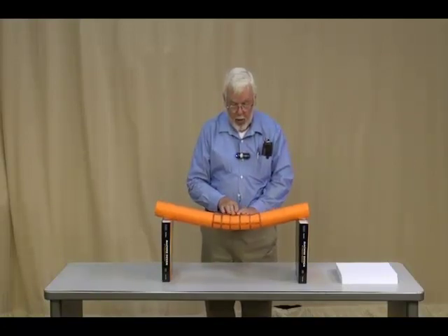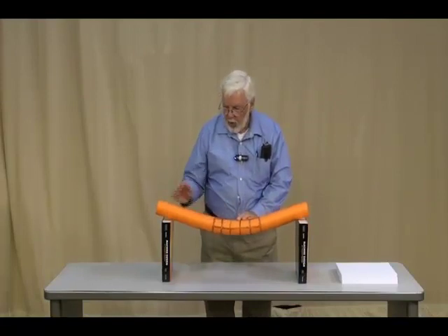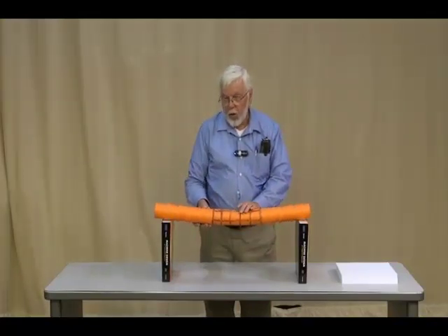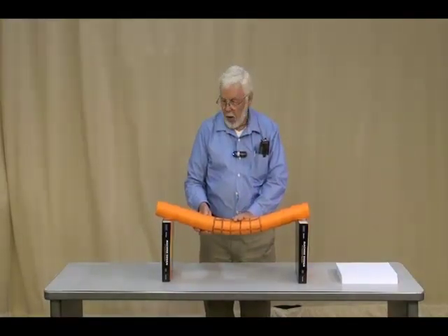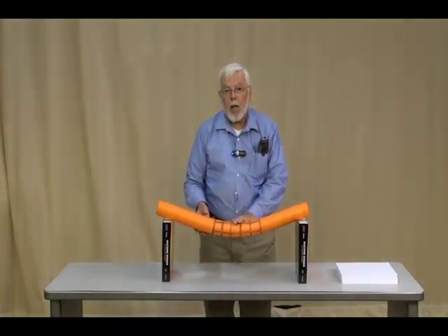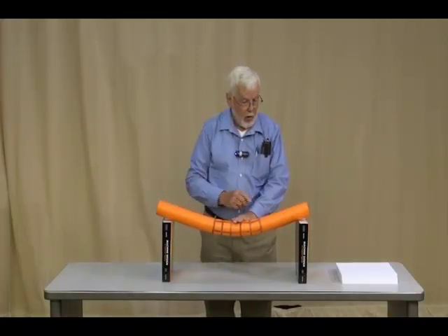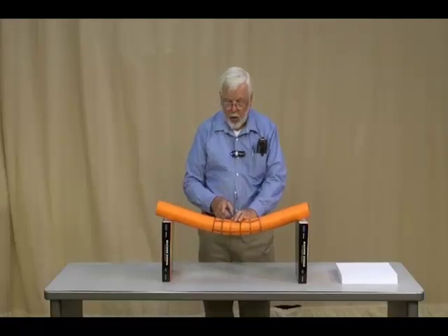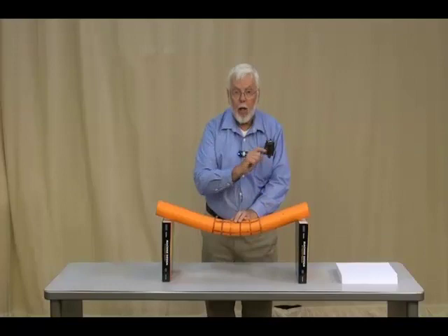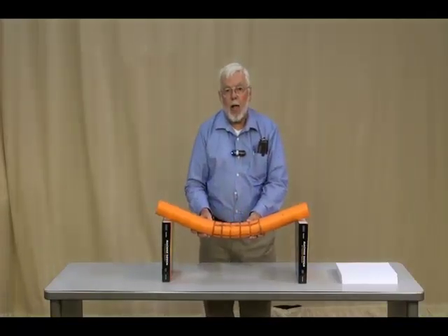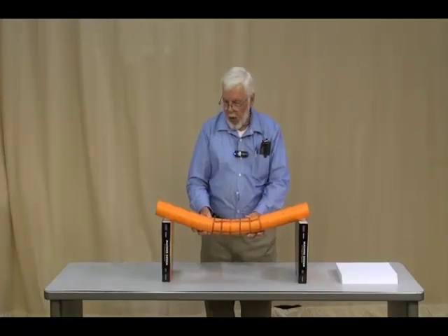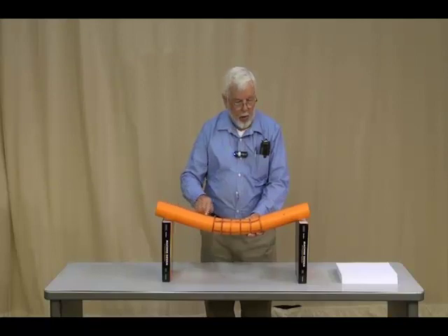And you can see the bend in the lines. But notice the ends. This end over here and that end over here are no longer parallel to one another, nor are they vertical. So the ends of that beam are changing angle, and in fact what they're doing is remaining perpendicular to the center line of the beam, which is now curved. The center line of the beam is called the neutral axis, and all of these sections, including these lines that I've drawn here, here, and here, and here, are remaining perpendicular to that neutral axis, or center line of the beam.